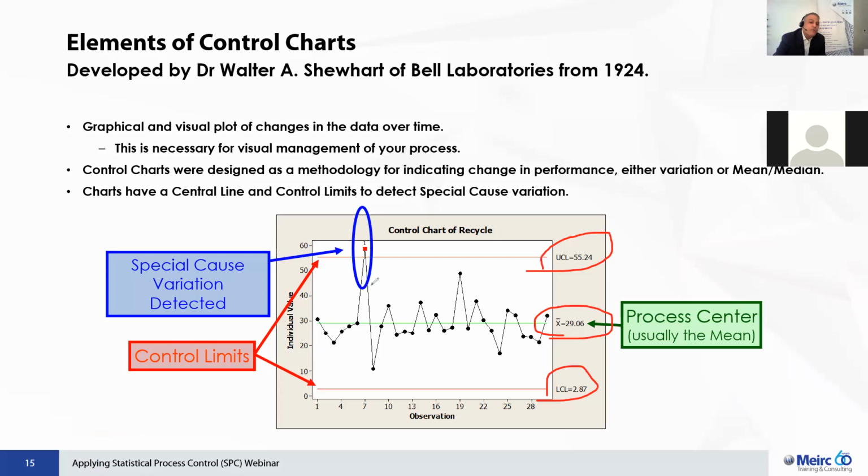And immediately from that variation chart, you can see, maybe this point that is showing me something out of control. This is a special cause. We need to investigate, and we need to understand why did it happen. If we can understand, if we can put a corrective action in place, then we might be able to remove it from our calculation and regenerate the chart. But there are sometimes an acceptable percentage of special causes that might appear in any process, and we might accept it as part of the process itself.